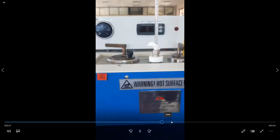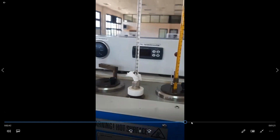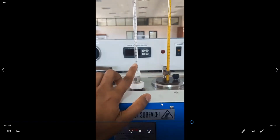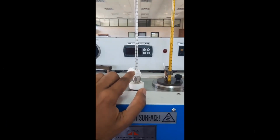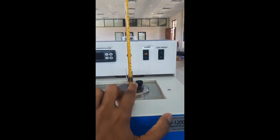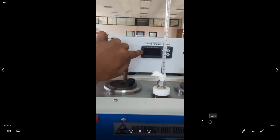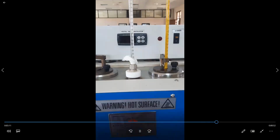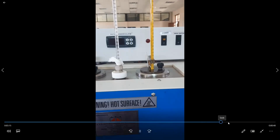We heat up the water inside the tank, and we need to measure the temperature of the oil and the water. From the outside we can measure the water temperature, and here we can measure the sample oil temperature. This is the main switch, and here this is a digital thermo calculator. From here also we can observe the temperature of the water. But we have to give some time to transfer the heat from the water to the oil sample.